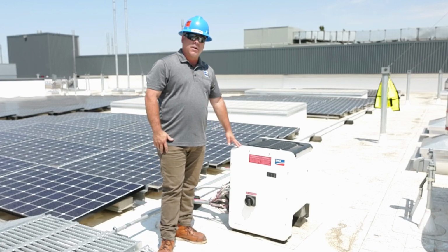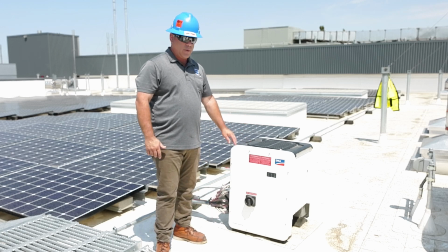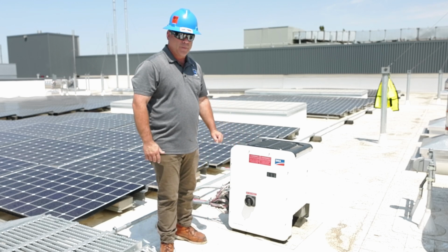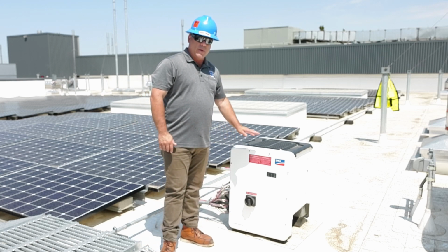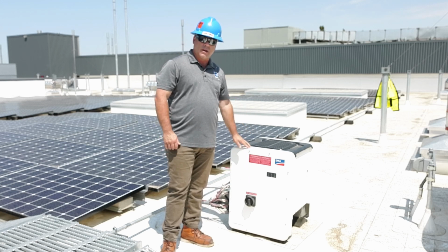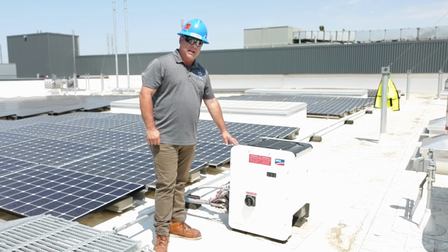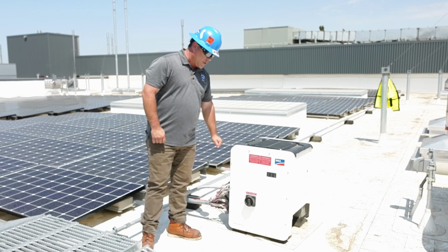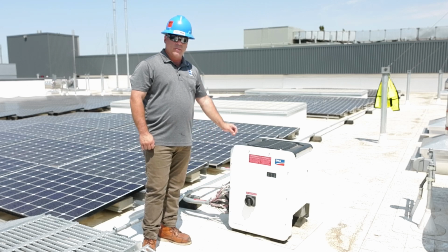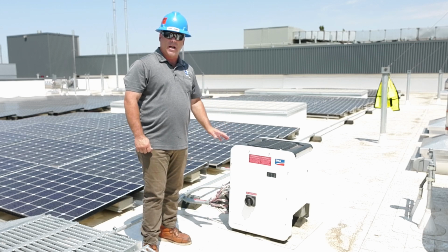If we need to do a software update, that's when we do it. We have to just connect to the tablet and request the software update. If we do that, it can take up to 45 minutes. If we want to reset it with a tablet, it'll take between 3 and 5 minutes to reset it, and then it'll go through the startup process that it takes 5 to 10 minutes. It is not recommended to open up any of the strings under load. You need a particular tool to determine from the inverter. Again, not recommended. It's good to do it at night when the panels are shut off.